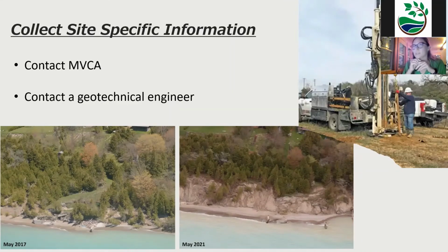If you wanted more in-depth and detailed information about the stability of your property or structure, we recommend contacting a geotechnical engineer. So they actually drill boreholes into the ground and get an idea of soil composition, soil moisture, and they can kind of give you a better idea of what failures they think might happen. So maybe they can give you a better idea of, would it be a large rotational failure, or is it more just landslide failures, and give you a better idea of those types of things and maybe the timing and then the actual stability of the property.